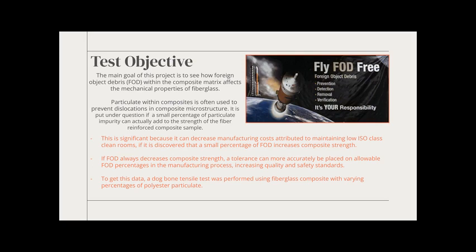This is significant because if so, manufacturers would be able to increase the ISO classes of their cleanrooms, decreasing manufacturing cost. However, if FOD always decreases strength, then a tolerance can be placed on the allowable amount of FOD in the composite, increasing quality and safety standards of the manufacturing process. To get this data, a dog bone tensile test is performed using fiberglass samples with varying percentages by mass of polyester particulate, or glitter. Our test is innovative since it can be done on a small, inexpensive scale.